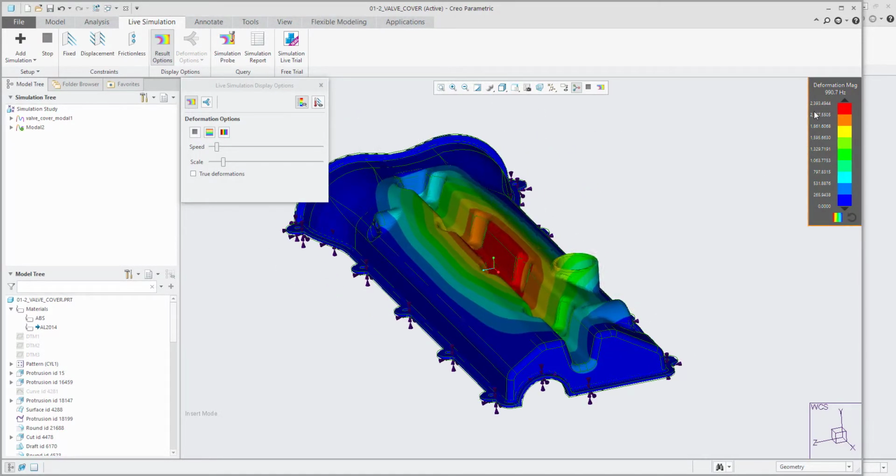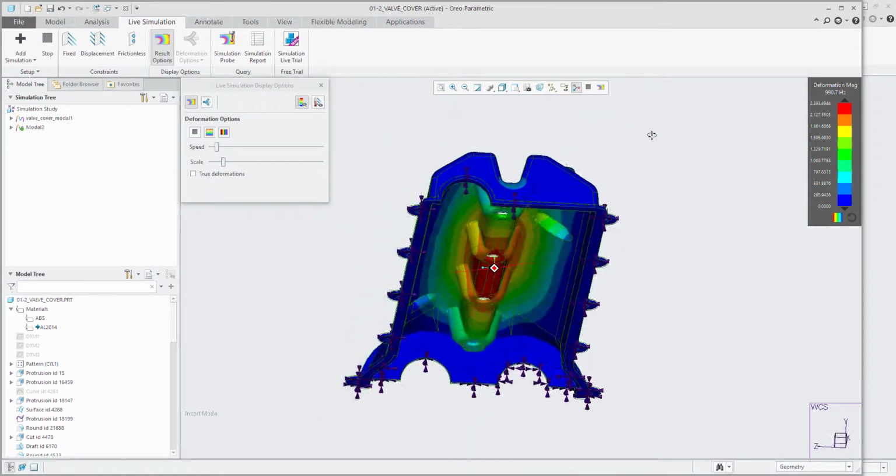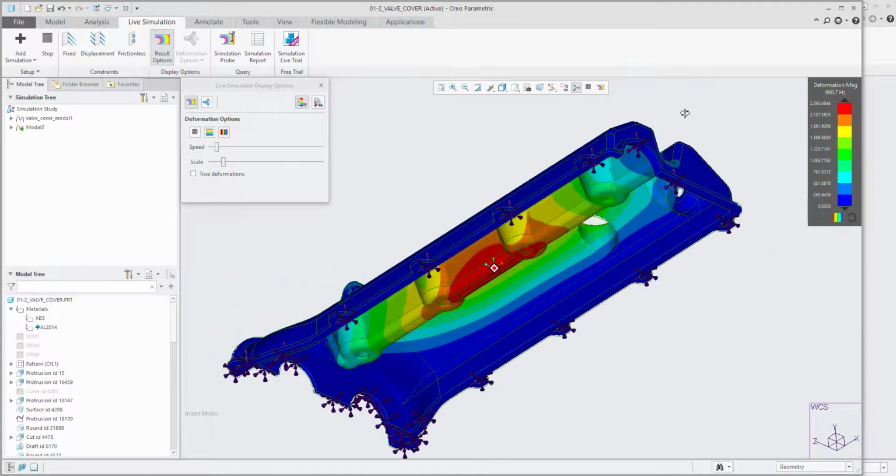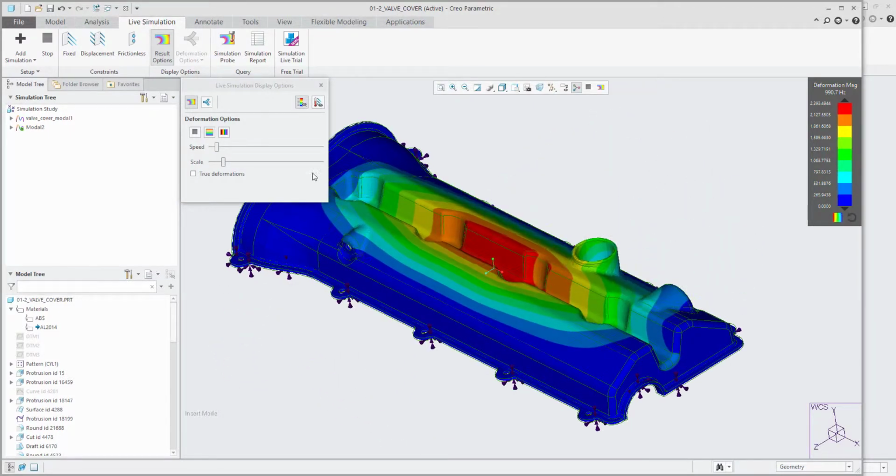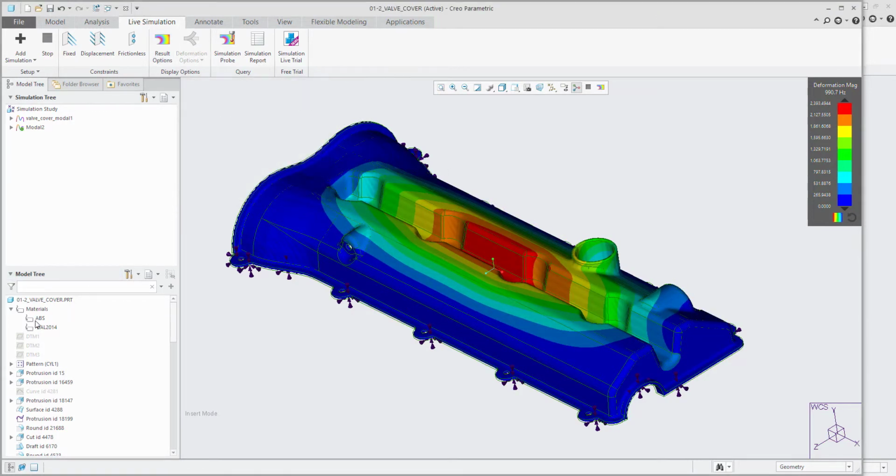And the natural frequency of a part always gives us an idea of the stiffness, and also how it wants to vibrate in certain ways. Anyway, the stiffness value can kind of be set there. So what I might want to do now instead is compare it to if I use some kind of plastic, like an ABS plastic.